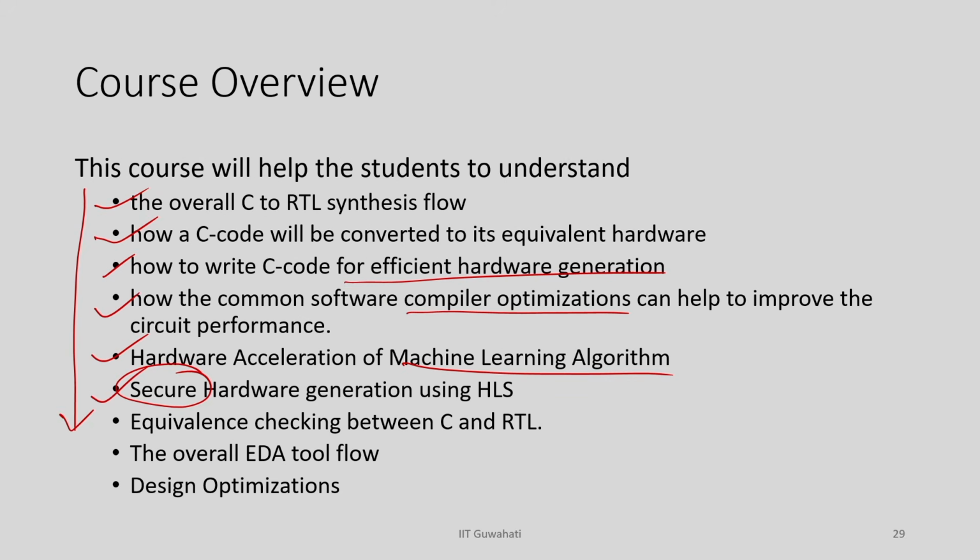And then I am going to talk about the verification of this RTL, because once you convert a C code into RTL, you have to make sure it is functionally correct, right. So, your RTL is exactly functionally correct with your input C code, and that is where I am going to talk about how you check that, the equivalence checking between C and RTL.